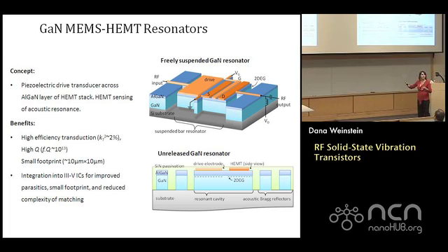And we can fill in regions with, say, silicon nitride passivation, possibly alumina passivation, as we learned that may give you much better stability in terms of your HEMTs. And this has several benefits, because primarily the thermal conductivity of a released structure is pretty bad, right?